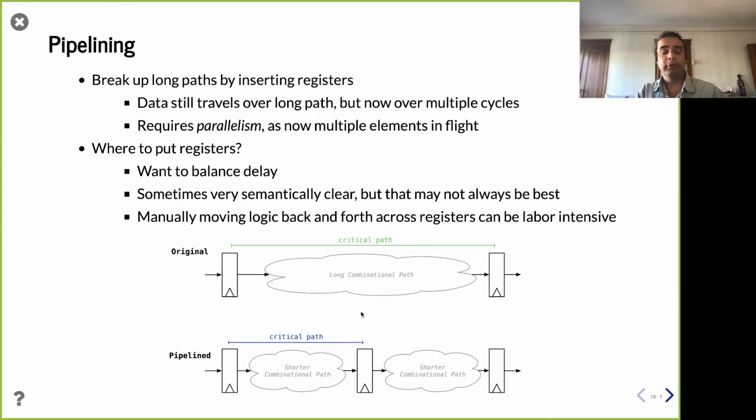And also remember that when the tools are optimizing your design, they're going to be changing which gates and how they're mapping and optimizing certain portions of the logic, right? So it's almost like you're trying to move around water, where you can push it aside, but in a second it comes flowing back in. It's like that, trying to solution around these registers, where it's a little bit hard to converge and optimize this sometimes. It's very labor intensive trying to figure out where to put these registers, not just to even put them in your design. They're feasible to put in the design, but like I said, in some cases you can't because of hazards. So how can you mitigate those hazards? In other cases, it's just hard to know where to put them.